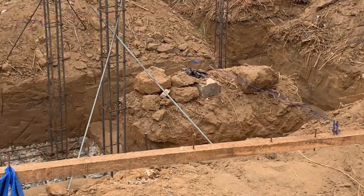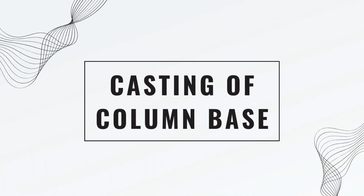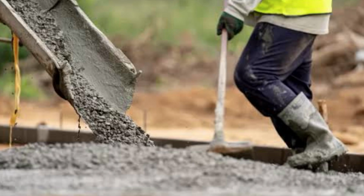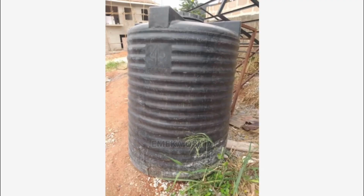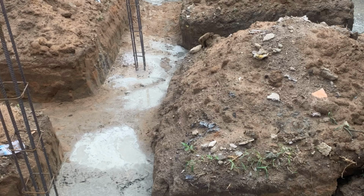And that will take us to the next stage, and our next stage is what? Casting of column base. The casting of the column base is the second stage after mounting of the reinforcement basket and columns to their respective positions. This process involves what? The mixing of sand, cement, aggregate, and water in a specific concrete ratio that will be gotten from the structural details.